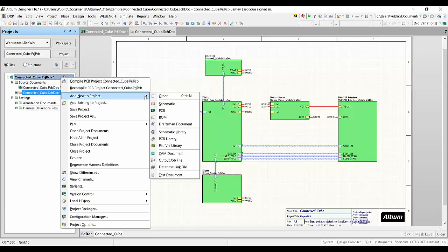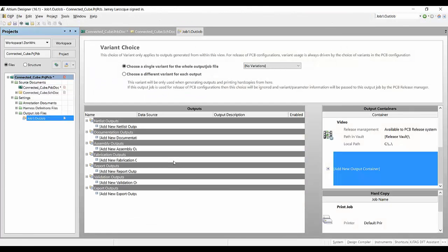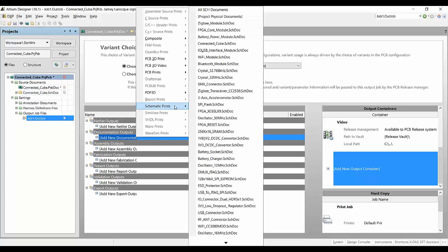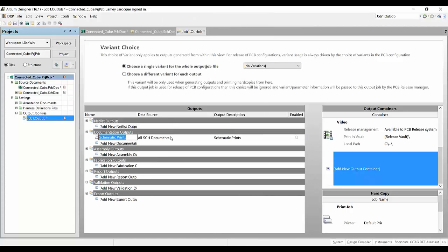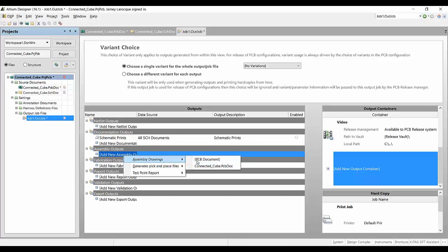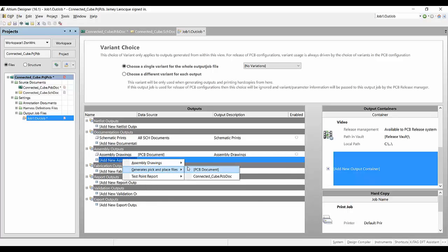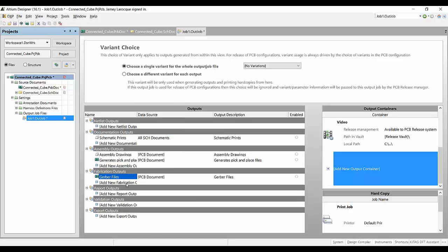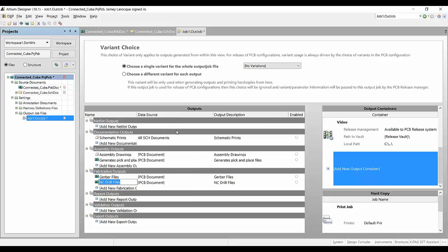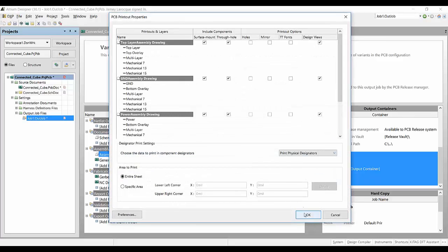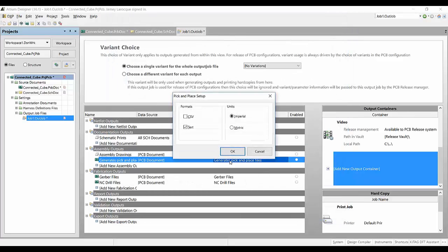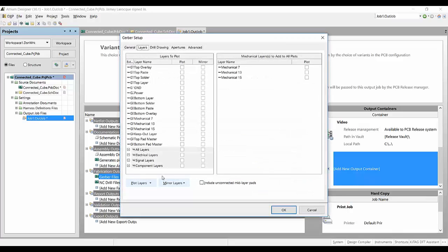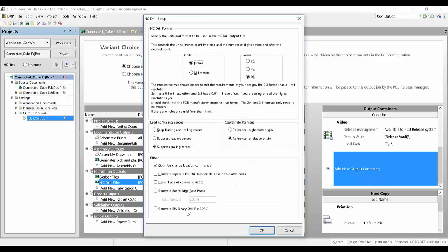When you're ready to push your PCB design to production, you must gather all manufacturing outputs and documentation that your PCB fabrication house desires. You must be cautious during this process to ensure that you have not selected previous revisions of your documents or the wrong ones in general. Exclusive to Altium Designer is the output job. You have the ability to configure all assembly and manufacturing documentation under one unified platform, and these outputs travel with the design, preventing data loss or the selection of the wrong file, taking away the manual pain and human error.